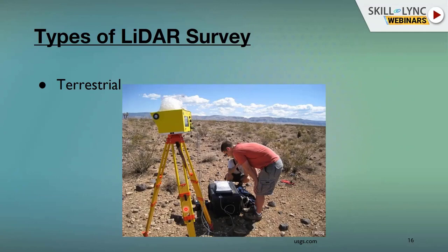Based on this, the price varies, and the accuracy and system integrations also vary. Do you think the terrestrial LiDAR scanner gives millions of points within a second? If it is rotating 360 degrees, it gives very real-world pictures, 3D panoramic images and point cloud data.